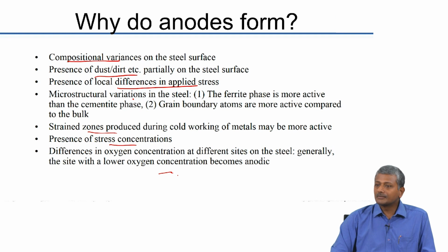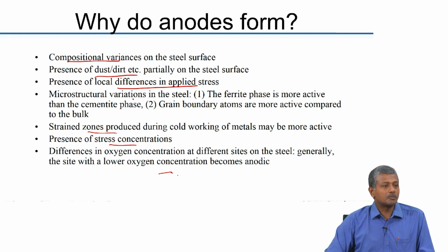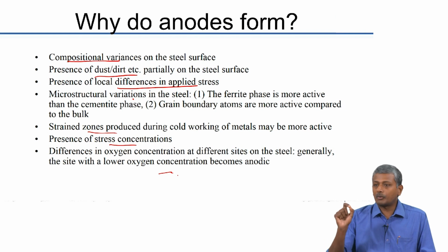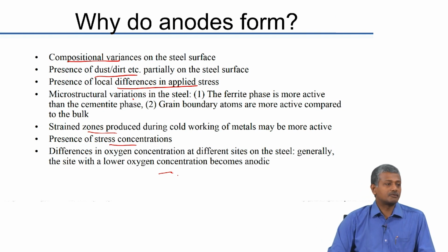Epoxy coating, another problem is that if you do not coat the epoxy properly on the steel, if you leave some zones, pinholes or blisters are created on the steel surface, and those are the zones where epoxy is not coating the steel, and you can directly create a difference between that point and the rest of the steel surface and start initiating the process of corrosion. So, need to be extremely careful with the use of steel. Unfortunately, in job sites we do not seem to pay much attention to these very simple aspects.